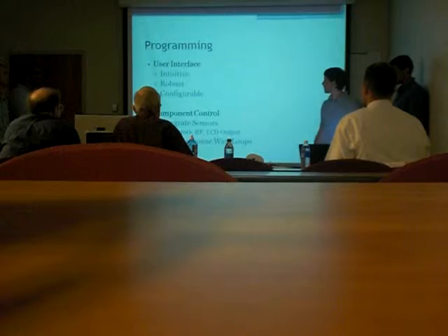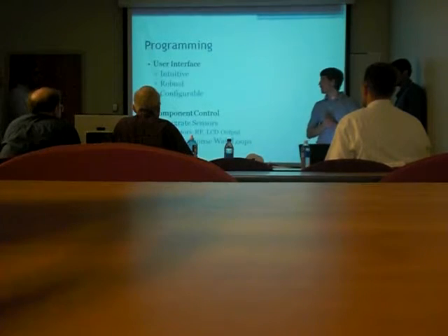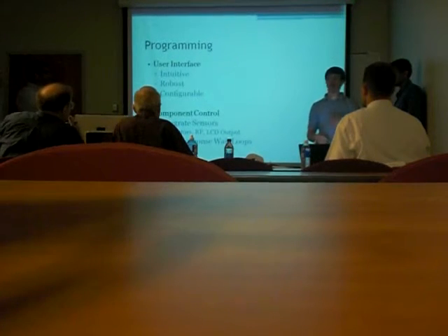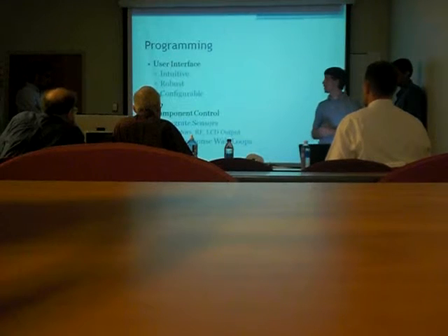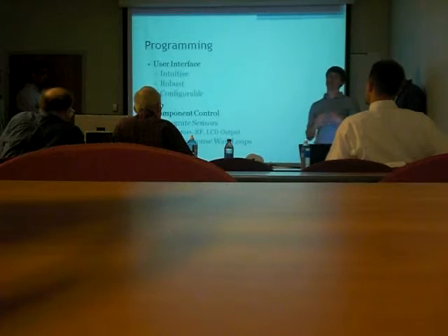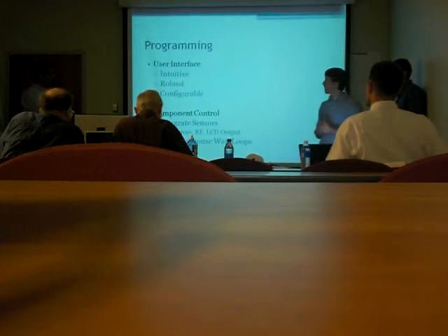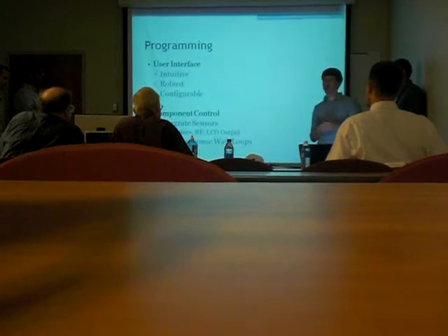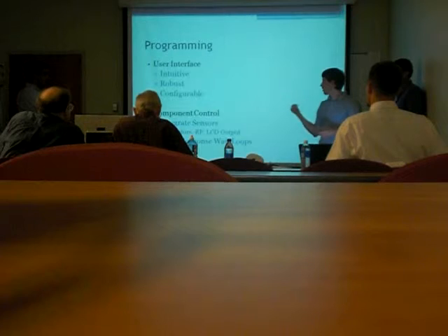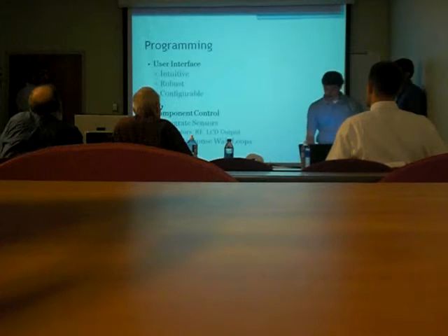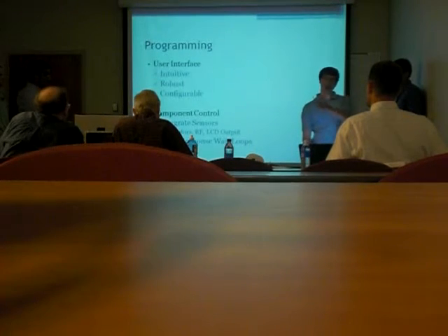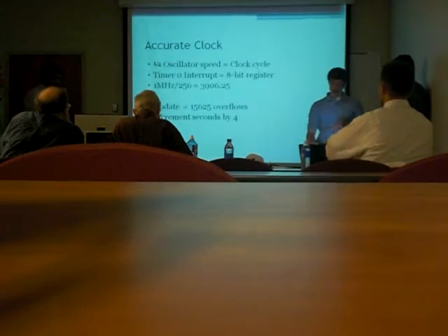As for programming, I approached it by first looking at the user interface. I decided it had to be intuitive, as in easy for anyone to use, robust enough to handle various error inputs from the user or if there was an error in dispensing, and configurable so that they could change data or update it as they went along. Also, component control was integrated with sensors, in other words, the motors, RF, LCD output, and also input response loops waiting for, say, the cup being removed or a pill being detected.